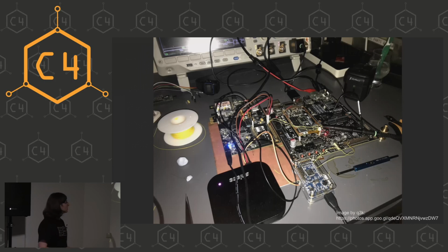This is the setup that Serge came up with. You can see the main board with all kinds of wires attached and oscilloscope probes. And this is just a UART adapter. And this is the FPGA board with a logic analyzer attached so we can see what's doing. And this board ran the FPGA bit stream, which sniffed the eMMC traffic, generated the trigger for the MOSFET that we hooked up to the voltage rail to pull it to ground, to short it to ground and take away the power for the chip.